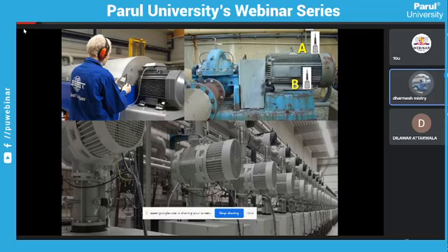We have to mount the sensors in all three axes, because the vibration can be in any of the three axes, X, Y or Z, and each vibration indicates a different thing. So here we have shown just an image of how the vibration can be measured.